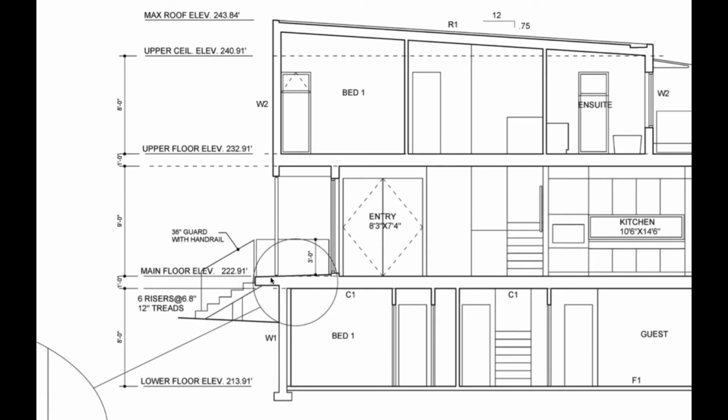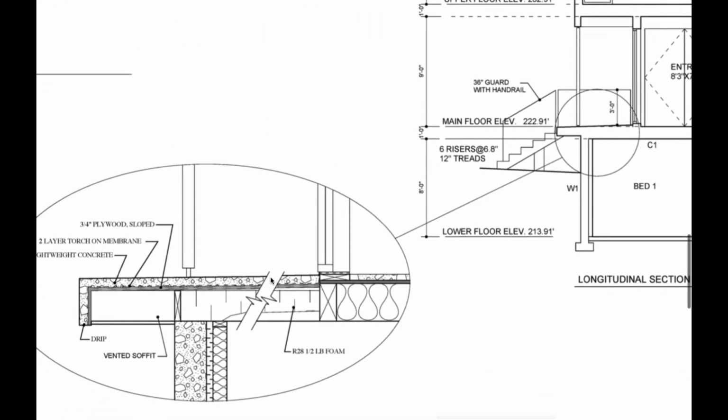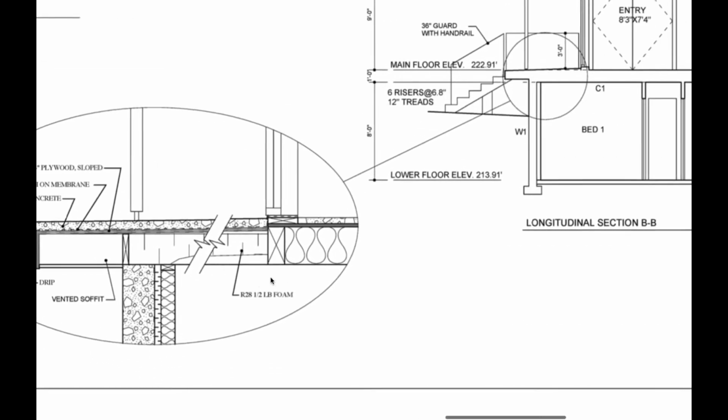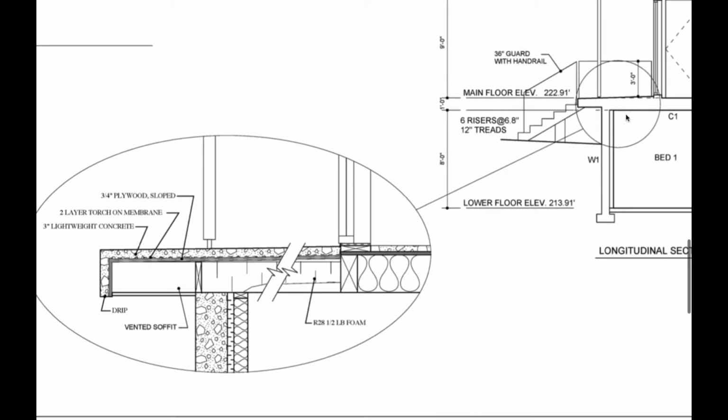Here you're going to have an exploded view, so I'll do kind of a screen here so you can see that you have your conditioned space in here, and out here you're going from a conditioned to an unconditioned space. So they need to make sure that the insulation remains despite the fact that you're doing a concrete wall with your rigid insulation and then your batt, that's for the basement down here.